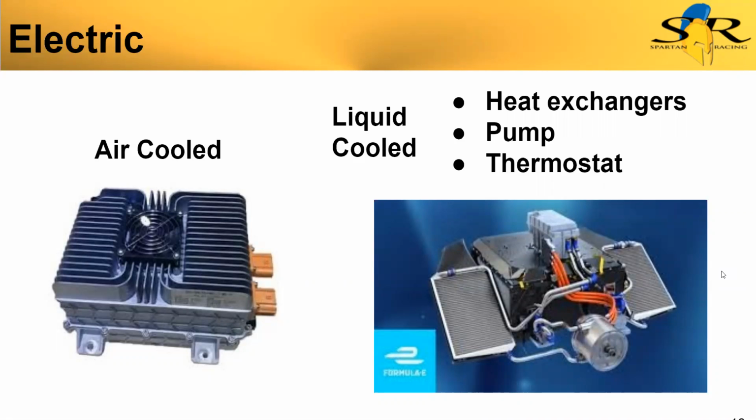Yeah, so if you're running them in series, it's just continuity, the laws of physics, that the same amount of fluid is going to go through each one. But you're right, in parallel, you do have to pay more attention to the pressures and use valves or orifices to control the pressure and flow. So maybe adding a little more resistance to flow to components that don't have a lot of resistance, so that they maintain even flow across each of the components.